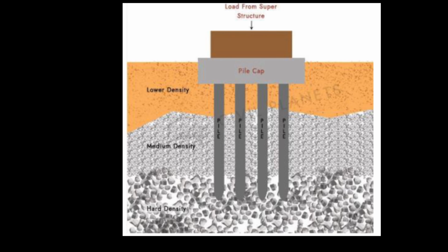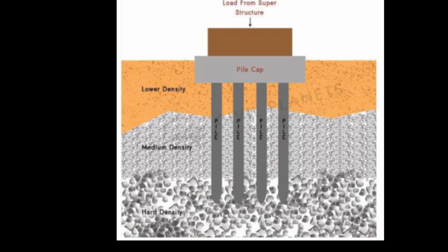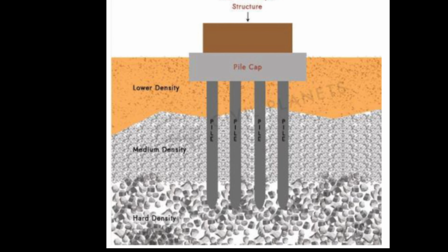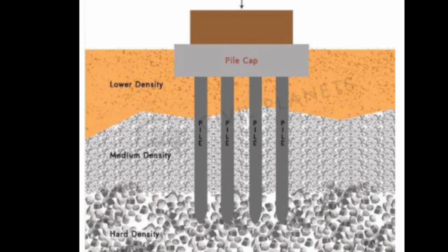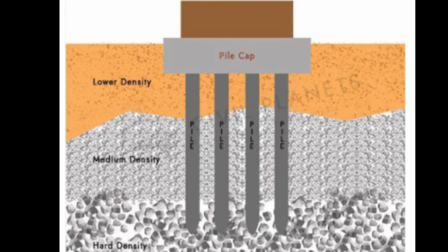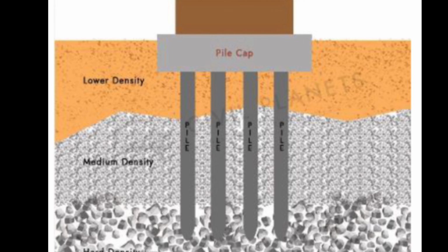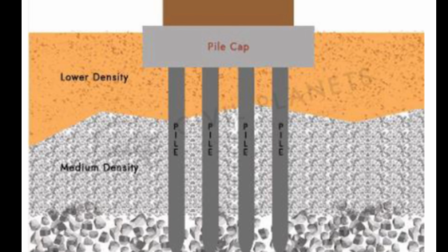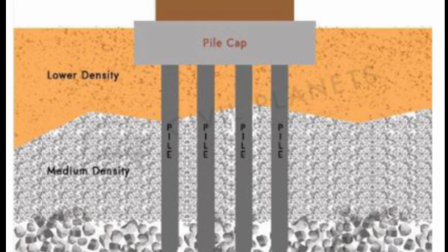Pile foundation. A pile foundation is a series of columns constructed or inserted into the ground to transmit the loads of the structure to a lower level of subsoil. It is usually used when there is unstable soil near the ground level. Piles are driven into the ground by heavy pile driving machines. A pile foundation constitutes a pile and pile cap, which is the slab for starting construction of columns and walls.